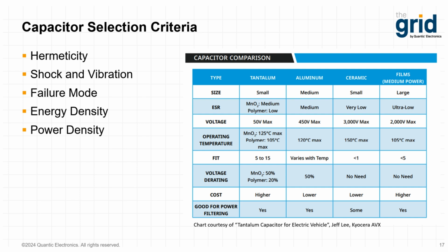Now, like energy density, power density is measured by calculating the energy delivered by the capacitor per unit of time. Some applications are so volumetrically constrained that they can be really sensitive to power density. So designers must confirm that the capacitor can handle the application's required power needs, which is typically done, again, by getting in contact with the manufacturer. You can look on their data sheet or their website, or just contact them directly. Once you confirm the power, you divide that by its volume, thus giving us the power density.